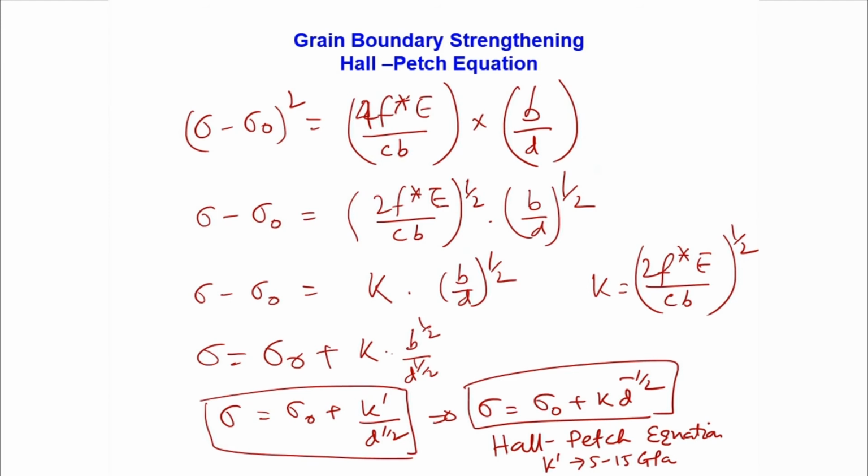So that means as we go down to the nanocrystalline grain, the strength will increase drastically. That is why we come back to the nano size. As you know, D is to the power minus half, so the effect is more significant. This is not linear. The effect is more significant because of the factor half, and this is inversely proportional. But this can happen very easily only till a critical grain size, below which it is no longer possible. We will come back and discuss that aspect also.